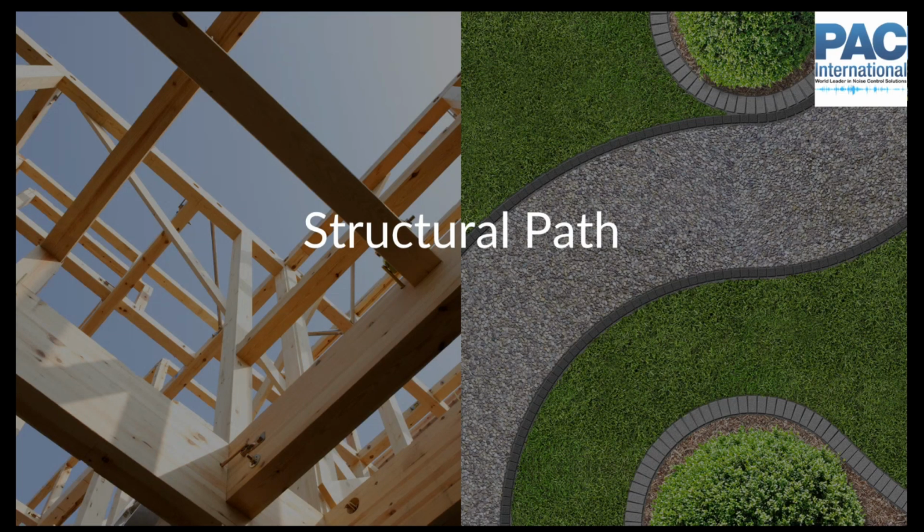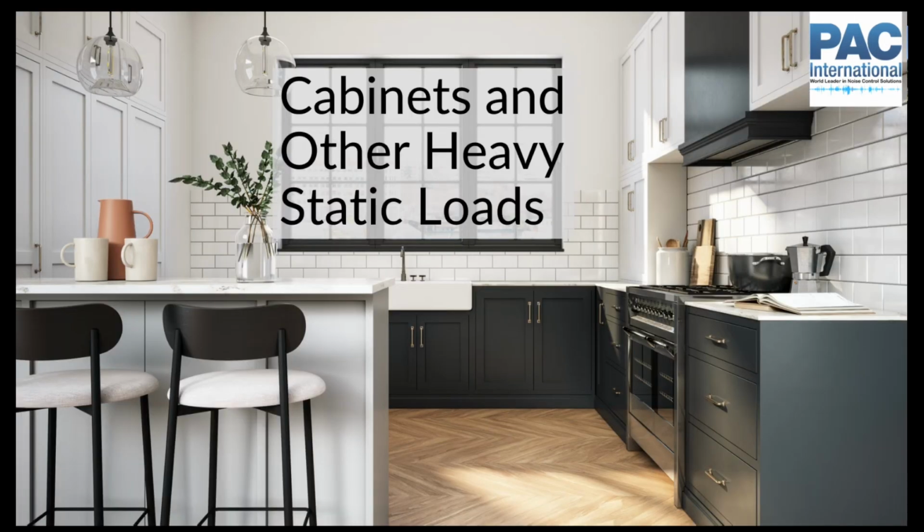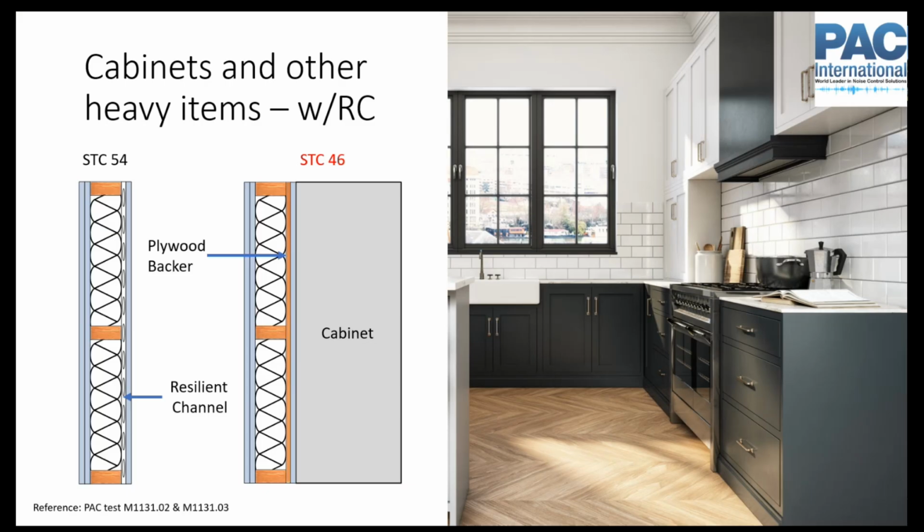All right, so now let's talk about some structural paths. The first one is mounting cabinets and other heavy static loads to a wall. Say you've got a typical resilient channel demising wall. If you're going to mount cabinets to it, the typical way of doing this is using 1/2 inch OSB or plywood, because the resilient channel creates a 1/2 inch standoff from the studs.